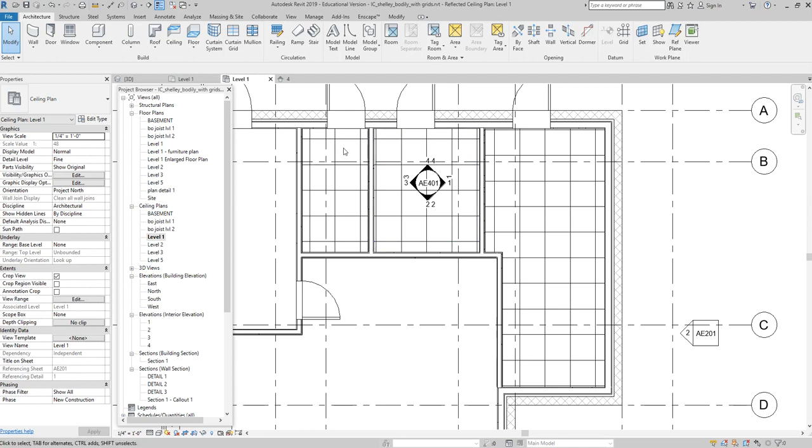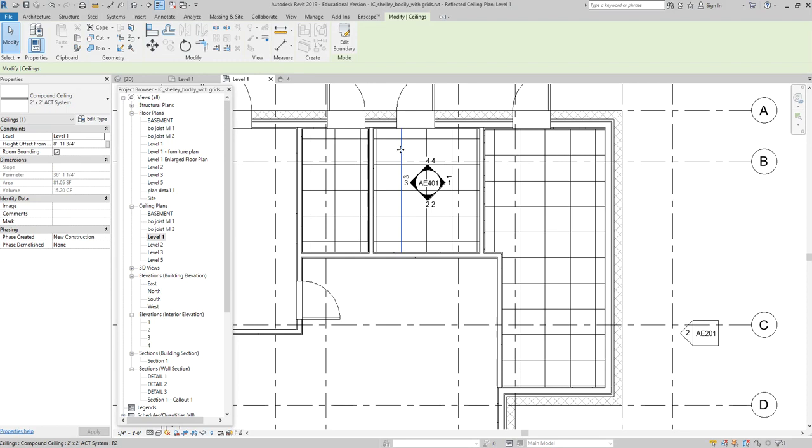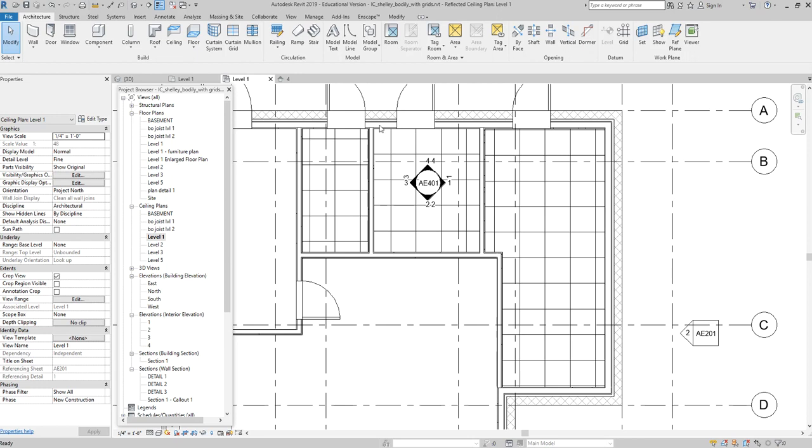when you do the auto sketch, they've gotten smart. It didn't used to do that. This does actually look like it's centered, so that's pretty nice, right? But if I wanted to, I can click on one of those lines and drag it and change where that pattern falls, okay? So that's pretty nice. I can also align from room to room, so AL, click, click, and I can align those patterns so that they go from room to room very seamlessly, which is really great.